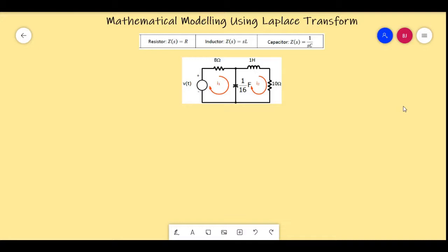You just have to remember our key things when doing Laplace transform. Hopefully, you still have a copy of your Laplace transform table, as that will come in handy when we convert voltage sources and current sources to their appropriate Laplace transform. Second, we must remember to convert our passive components into their appropriate Laplace transform or impedance equivalent, shown in the table above.